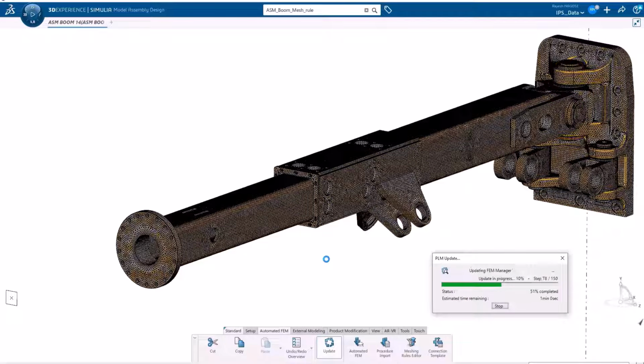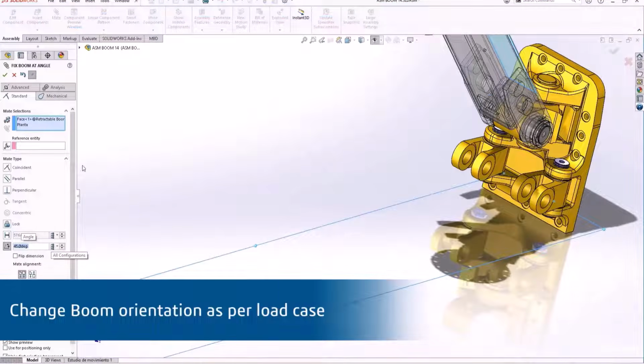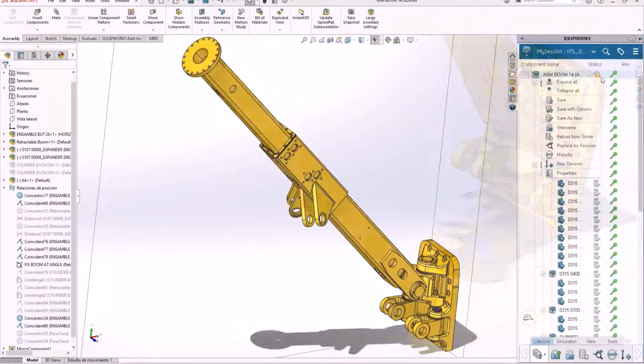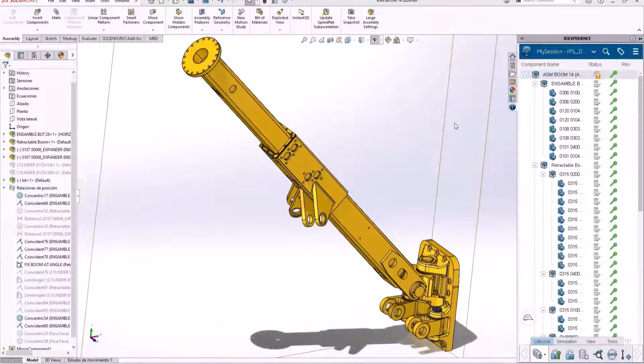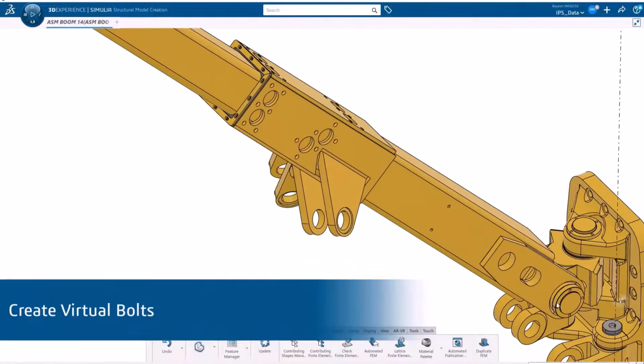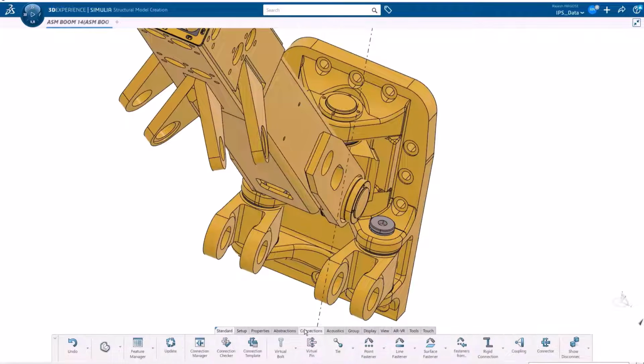And really, I want to drive this point home because at any point in this process, I can always switch back to SOLIDWORKS and make a design change like a distance mate here. To get that to update and flow, all I need to do again is right click and save in the task pane of SOLIDWORKS, and everything will update on the Simulia side. Now we've got materials and mesh. Let's connect this stuff together.